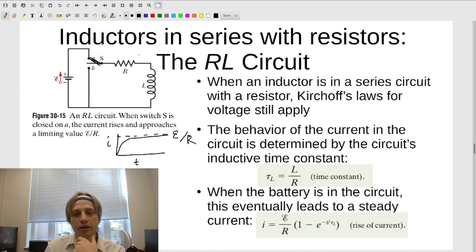And the idea here is that the bigger the inductance, the more magnetic energy it takes to essentially charge this up with magnetic energy, get it to its final magnetic energy, before you can start simply treating it as a wire, and then all of the energy coming out of the battery is going to be used in dissipating energy through that resistor.